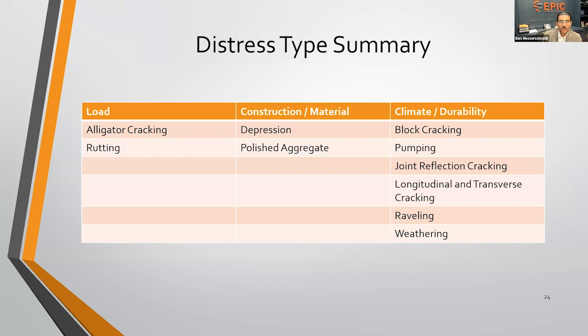So you can certainly expect that in a colder, more quote unquote extreme environment, lifespans of flexible pavement like asphalt would be reduced, and the climate impact would be much greater over the course of its lifetime, mainly because the salting of the roads is going to be way more aggressive than just some of the sea spray that you may get along either coast of Florida. But that's something important to consider. And that's also why different pavement materials are specified in different locations.